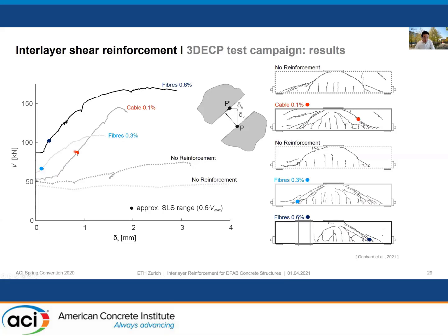And here at the serviceability range, which is this point, converted to crack width, we will have around 1 millimeter. This means that the serviceability design of these beams is more restrictive than the ultimate design.